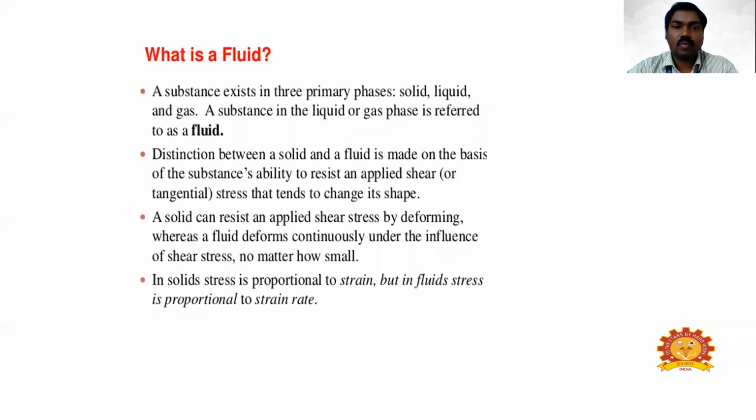So what is a fluid? A substance exists in three primary phases: solid, liquid, and gas. A substance in the liquid or gas phase is referred to as a fluid. The distinction between a solid and a fluid is made on the basis of the substance's ability to resist an applied shear stress that tends to change its shape.